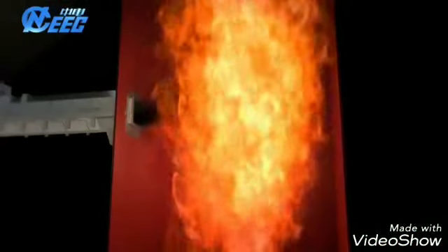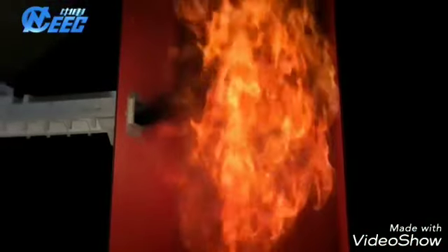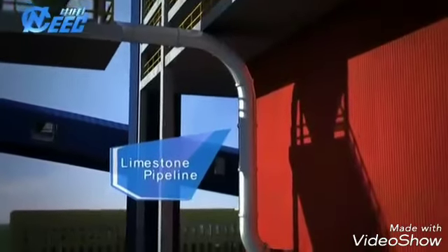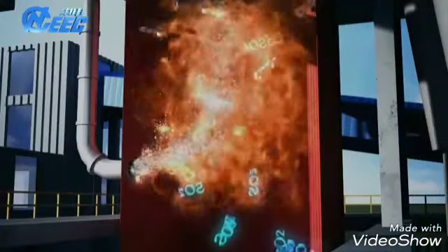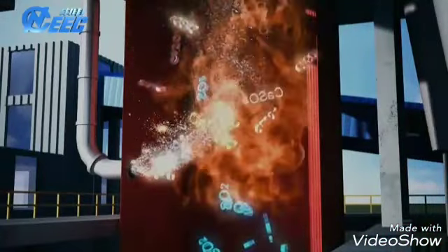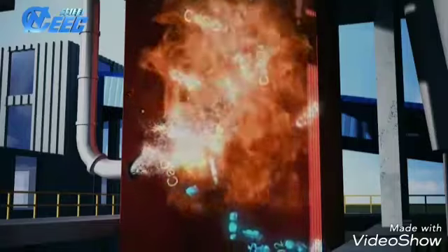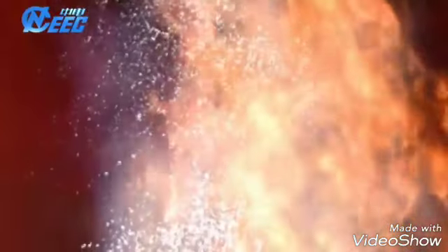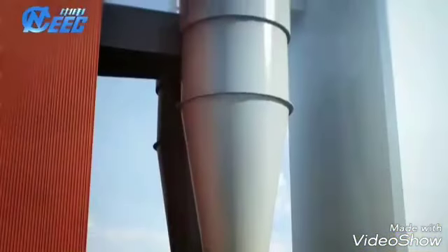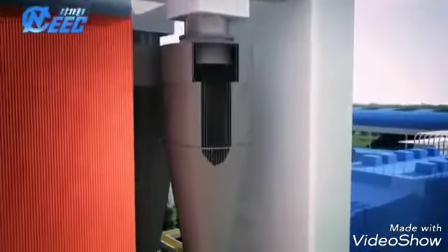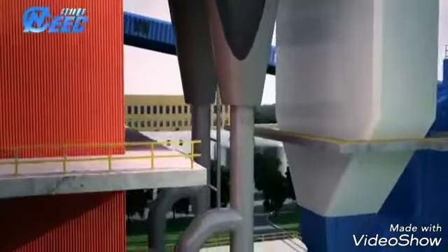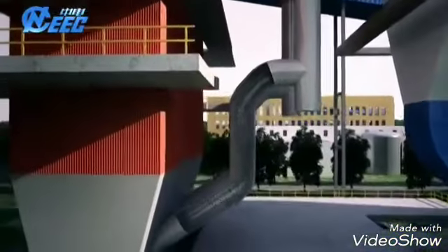Powder coal is ignited by oil torch. With limestone powder feeders running, limestone powder is fed and blown into combustion chamber by compressed air. Flue gas is forced into cyclone separator, and block slag particle is separated and fed back to the combustion chamber to burn again.